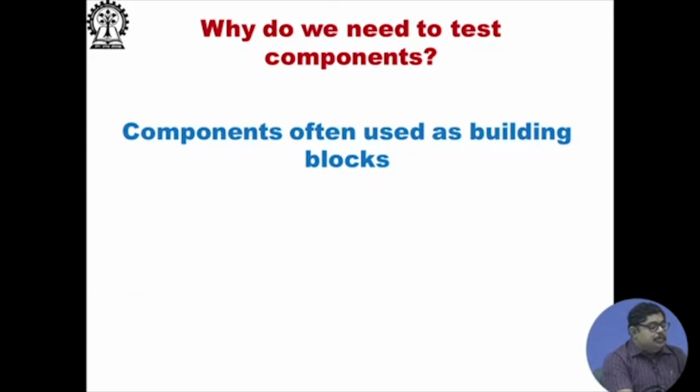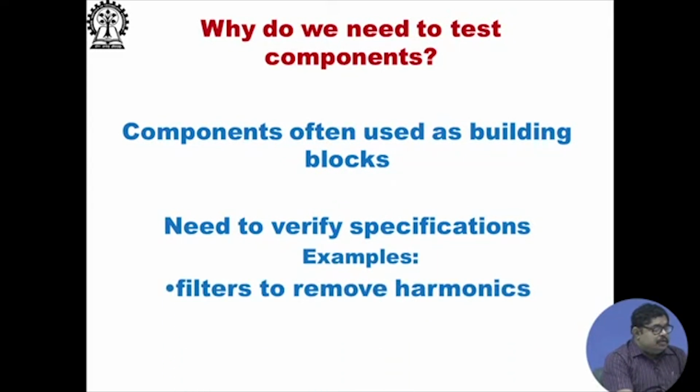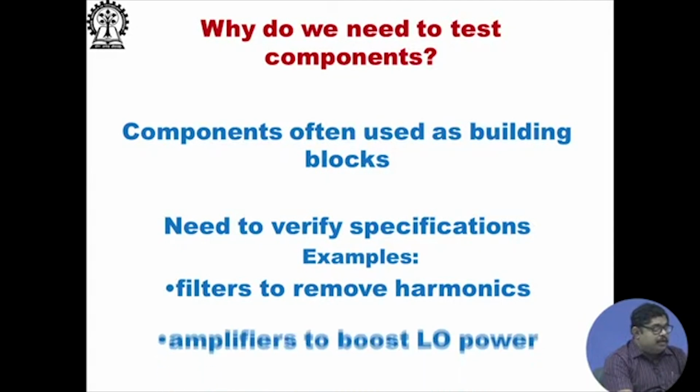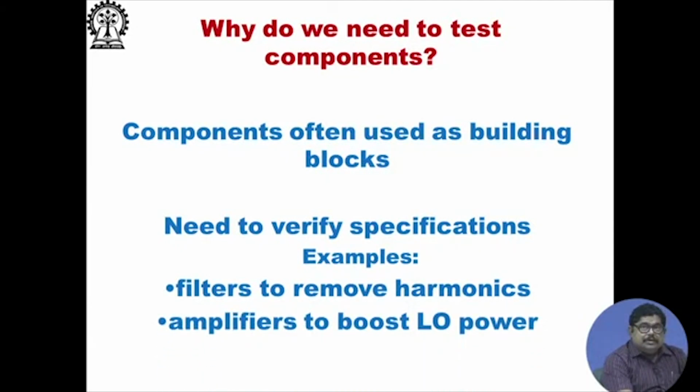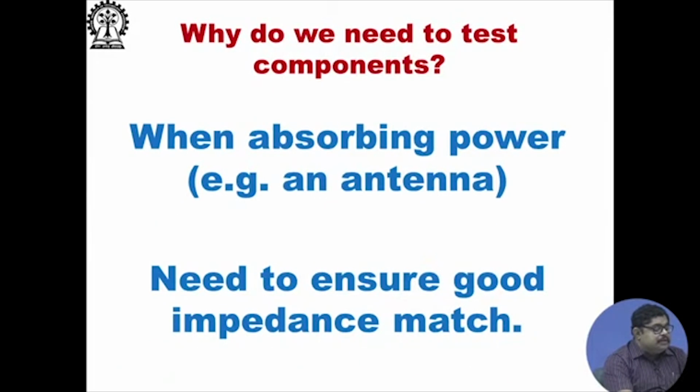At microwave frequencies, components are often used as building blocks. Now, we need to verify specifications, like filters. We need to see how much harmonics they are removing. Amplifiers, whether the local oscillator power is sufficient or not. Mixers, whether they are properly rejecting various signals.